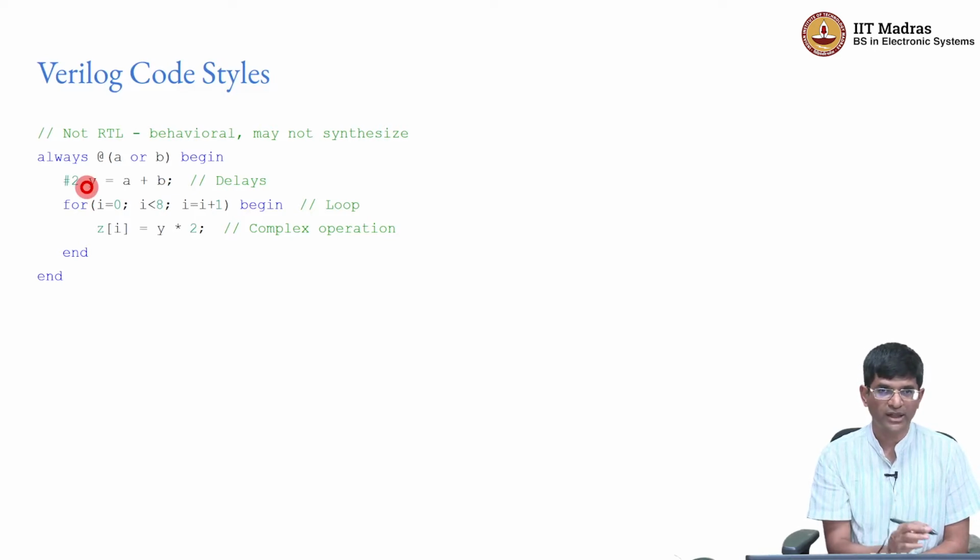Or to be more accurate, if you do want a precise 2 nanosecond delay, that becomes a fairly complicated piece of analog circuitry where you need to do a very careful matching of different lengths and so on in order to get that kind of delay, and it's definitely not what you intend if you think that you are trying to design digital logic.